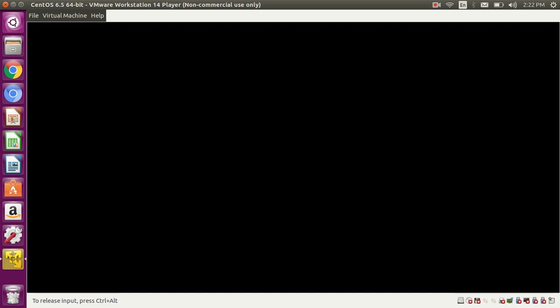Because of that I have got some 450 ps of skew or 600 ps of skew. Limit is 300, we got 550 ps of skew. So what we have done is, there is no interrelation, we have set max skew as 900 ps. It is not needed that we worry about what value to say about the skew, because the skew value is global. So the least path may be 100 ps or 400 ps, so you can say some random value, 600 ps.